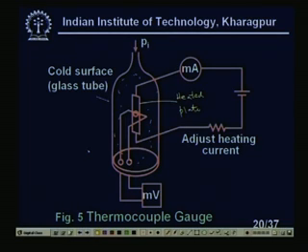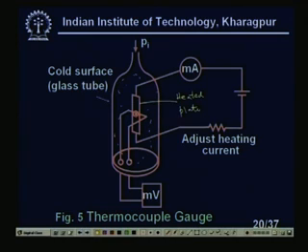Why? Because there is more chance of the heat being taken away, so the temperature will fall, and the thermocouple voltage will fall. So I will measure this temperature, and this millivolt output is calibrated in terms of the low pressure. That is the basic principle of the thermocouple gauge. This also basically depends on thermal conductivity. As the pressure increases, the voltage will decrease, because there will be less temperature rise, right.